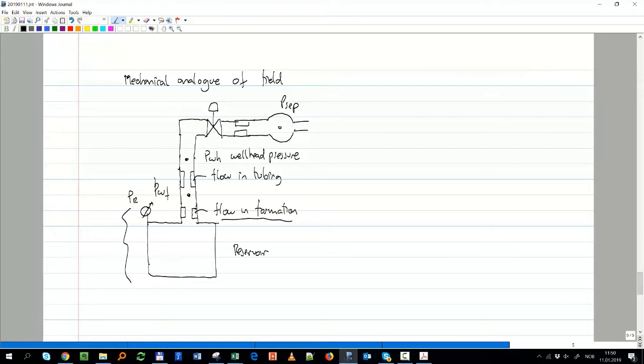What happens with time when I take material out of the reservoir? What happens with PR? It's going to decrease, right? So the flow through the system, here we have QO or Q gas. Q oil is a function of PR and P separator, among many other things. It is a function of that pressure difference. So with time, that is going to go down and down.